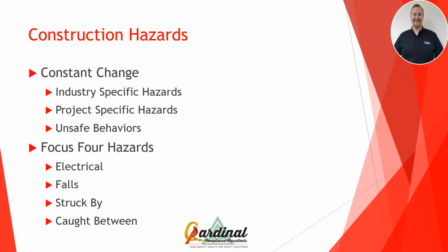For instance, if I'm working light commercial construction, my fall hazards are going to be different than if I'm doing heavy civil work. If I'm participating in steel erection, it's going to change the degree of hazard. Now, equipment operating, for instance, somebody operating a Bobcat, just building a standard strip mall. I'm worried about hitting other equipment, hitting people, damaging the building itself. Whereas if I'm working in refining, I'm a little bit more concerned with not just that, but what if we hit an H2S sample point where it's coming out 10,000 parts per million? So every industry, those construction hazards can change.